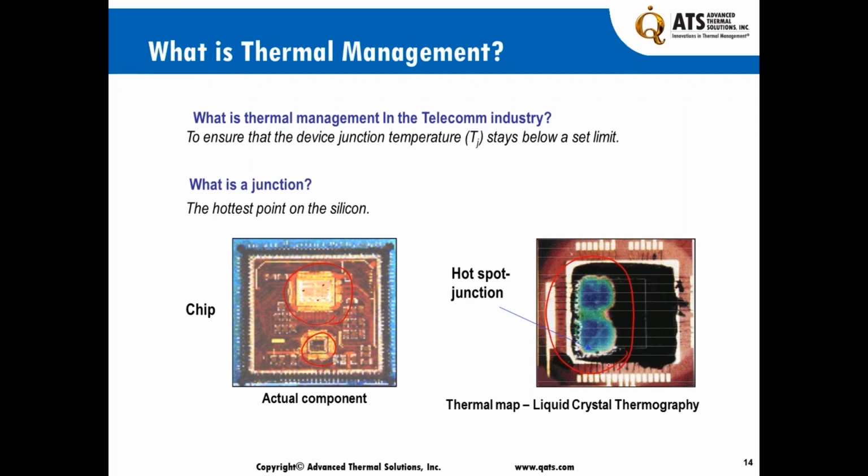Obviously, in liquid crystal thermography, you see the actual colors versus the manifested colors that you see in IR. So the whole notion is to make sure that the junction remains below a certain limit set by the device manufacturer, and that really puts the essence of thermal management and electronics cooling all in one scope. If you don't walk away with anything else from this webinar, take one bit of information, and that's junction temperature management.